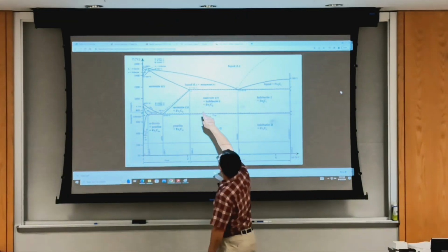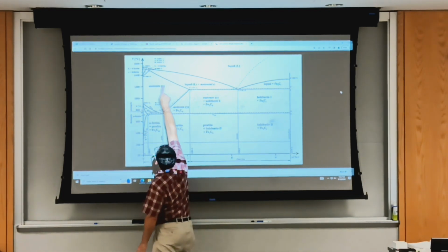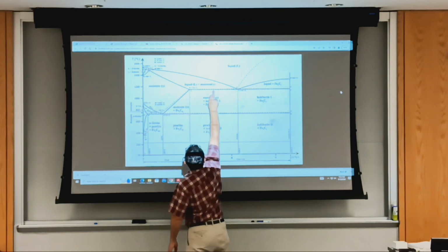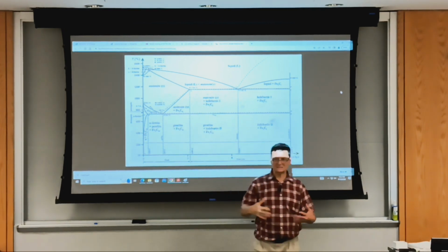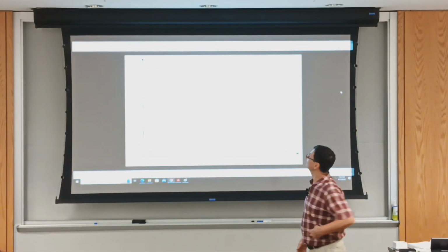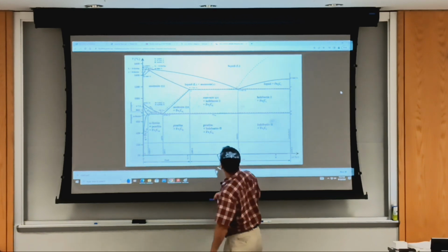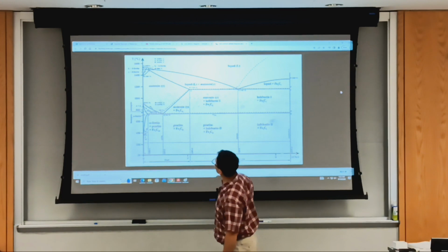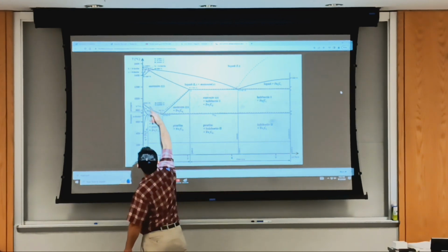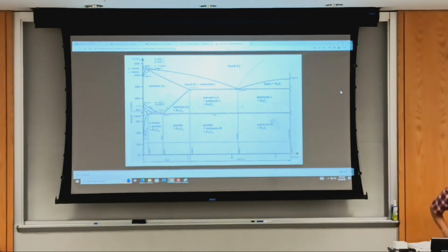They have a melting temperature lower than steel. So if you have a high carbon steel, you see the melting temperature. Irons melt at a lower temperature, and they are also less viscous, so they make for good casting materials. This is the eutectic point, the lowest melting point. And then various allotropic presentations for the carbon and iron in alloys.